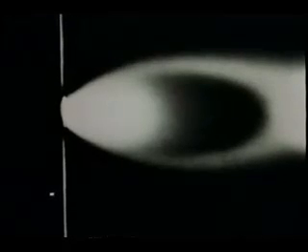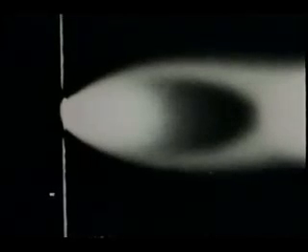The barrel shocks have spread out until they overlap and are mixed in with the Mach disk. Now only this hazy, slightly bright spot remains to remind us of the shock system. And now even that is gone. The jet molecules no longer collide with the background molecules, but fly straight past them to the chamber walls. The background molecules, for their part, can fly right through the jet without being hit. We have reached the free molecule limit, where the Knudsen number is large, and we see again that it is very different from the continuum limit.